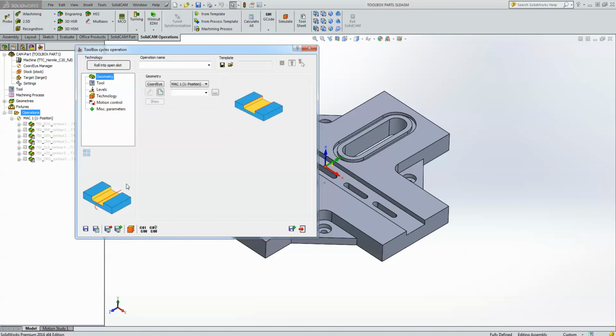Now, the reason why we have an operation like this, rolling into this slot, is because when speaking to tool manufacturers, I'll give you an example, ISCAR, we have tool manufacturers where they have end mills that have inserts in them. It's mostly and mainly very highly advised that when you use those inserts, not to go straight into the slot itself, but actually curl into the slot. This way you have a gradual build into the slot itself, avoiding that original bang going into the material. This is why we have what we call the roll into open slot.